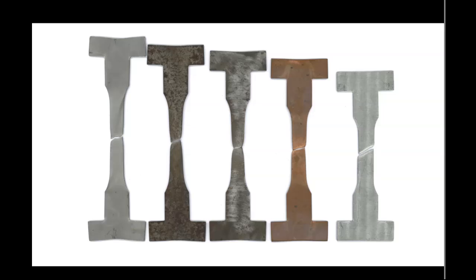Okay, so aluminium has a really sharp line, and this sharp line is a shear line that is at an angle. This angle is normally about 45 degrees. So this will be a shear line, and across that line there will be real defined thinning towards the shear lip. So the edge, it's called a lip, or the shear edge.